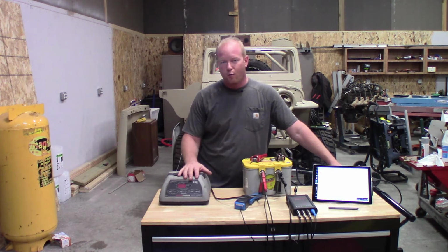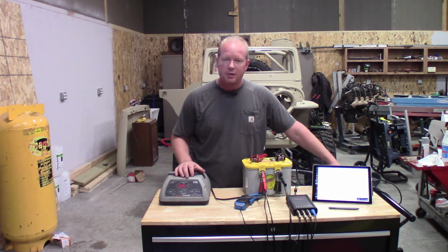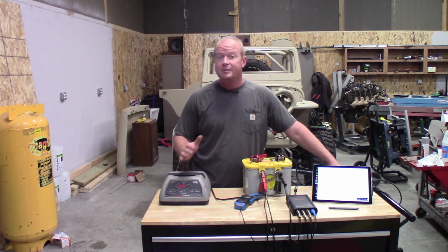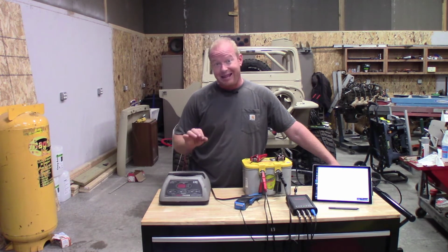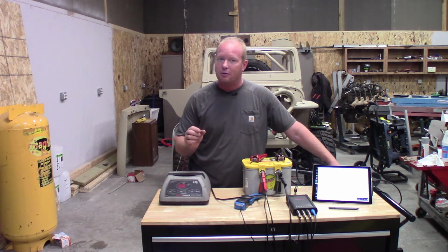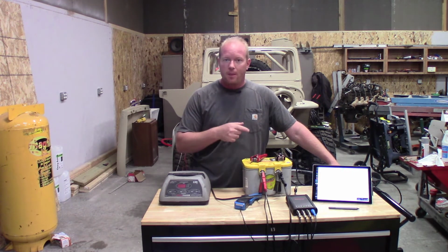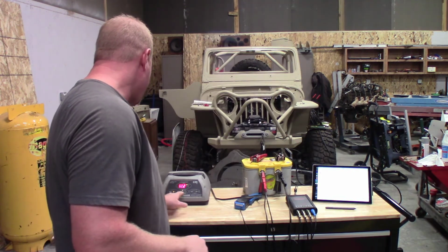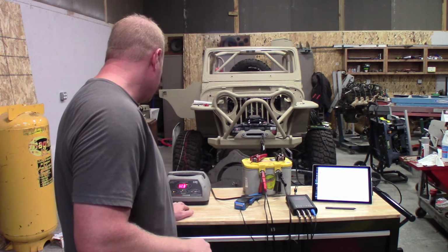Now I have switched over to this Schumacher. They call this one a speed charger. This one can be 2 amp, alternating between 10 and 20 amp depending on the battery, and an 80 amp start. So 80 amp start means that it can do 80 amps very momentarily. So let's get this one plugged in and see what it looks like on the scope. I'm going to change the battery setting to standard voltage, and we're going to do a medium to large battery.